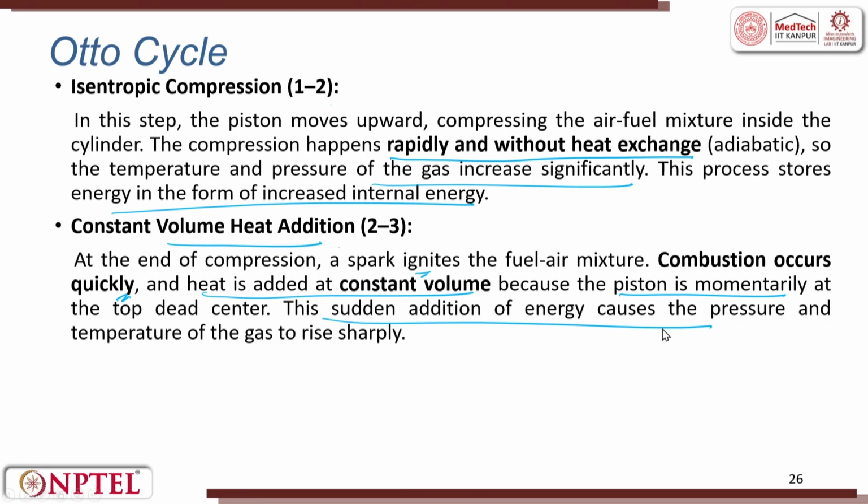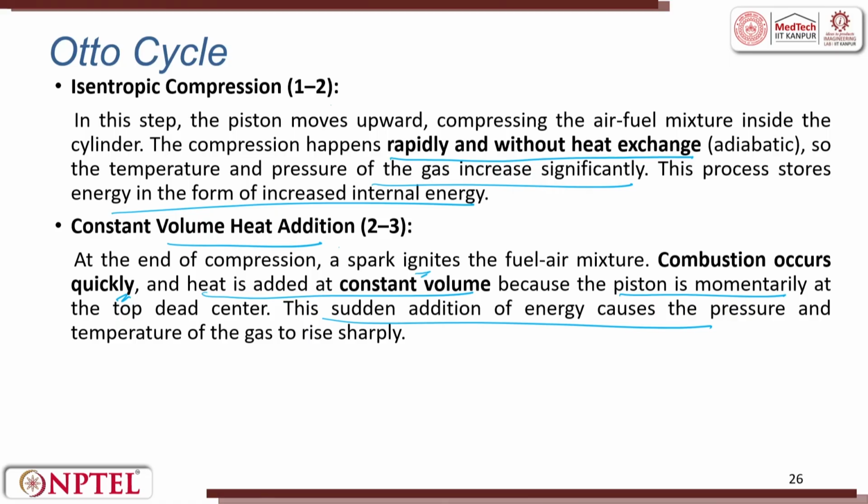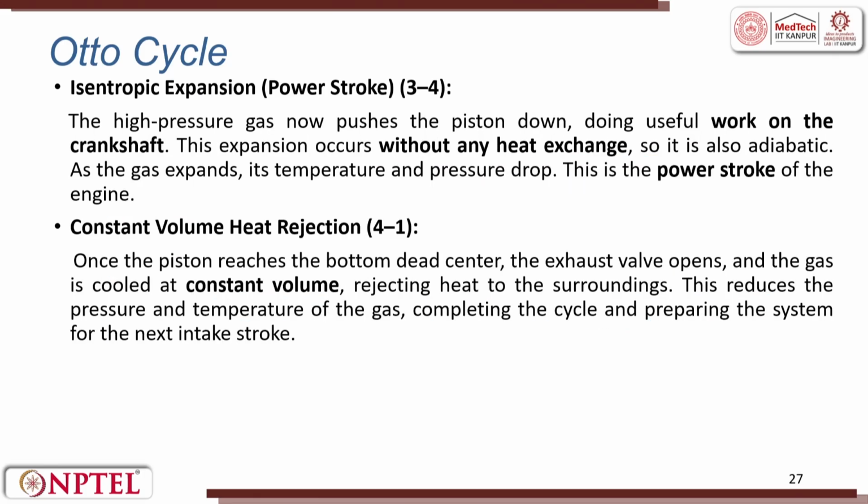So, constant volume happens when the piston is very close to TDC, and the combustion occurs quickly. When it is compressed, the spark plug fires and immediately the heat is added at constant volume, because the piston is momentarily at the topmost center. This sudden addition of energy leads to the next stage, expansion.